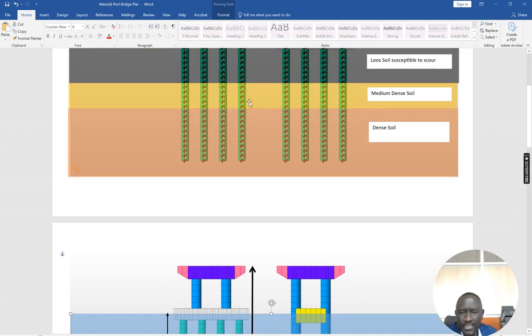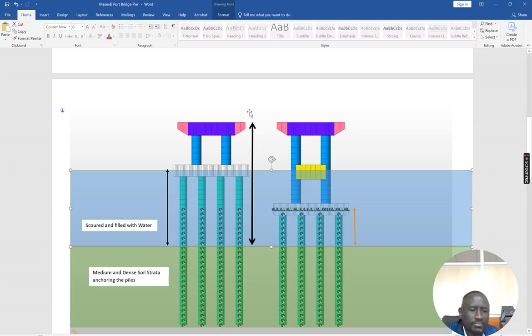water depth, depending on the soil parameter. If it is clay, which is a bit stiff, it holds water in a way. If it is silty sand, very fine particles can actually go. So basically, you may find the rate of scouring will depend on the soil type and the treatment around.